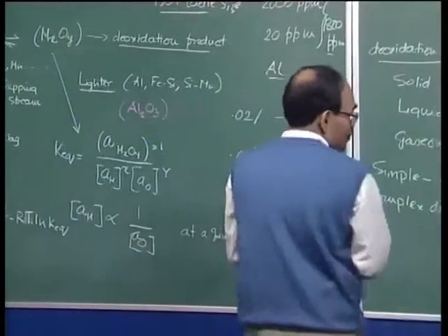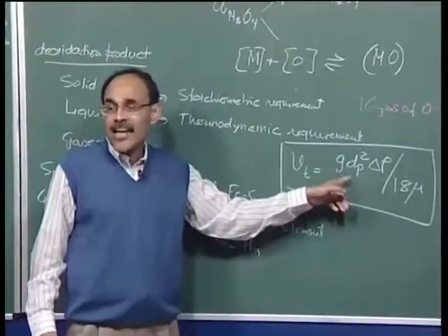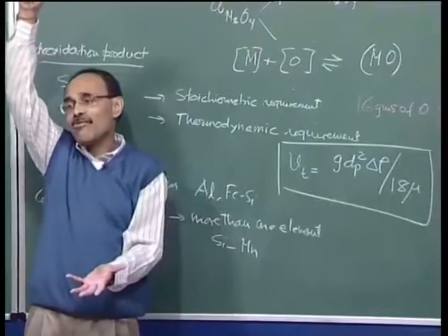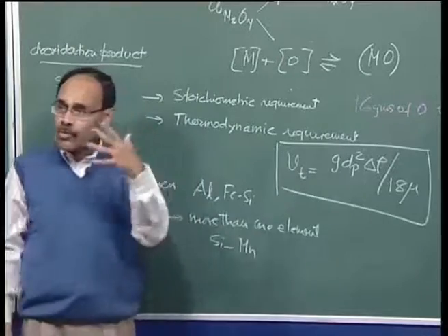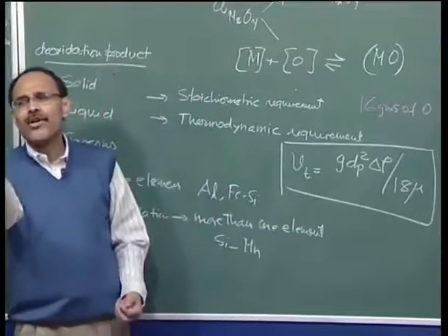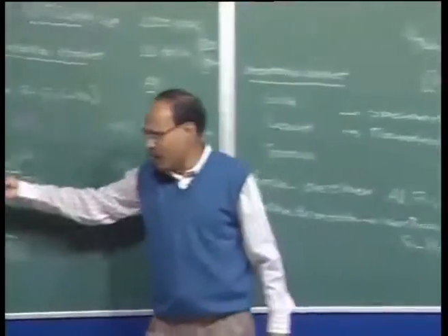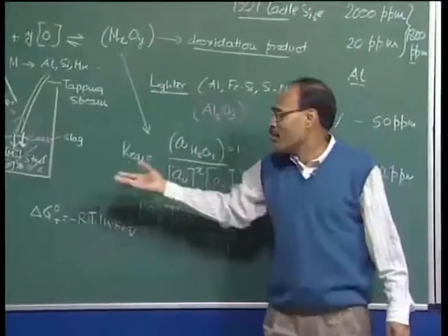So therefore, coming back to the Stokes law of settling, given the size range, and if I know the bath height, I should be able to find out the possibility of inclusion flotation. We can calculate and show that if the inclusions are of the order of 40 to 50 micron size, they virtually have no possibility to rise up and float to the free surface.